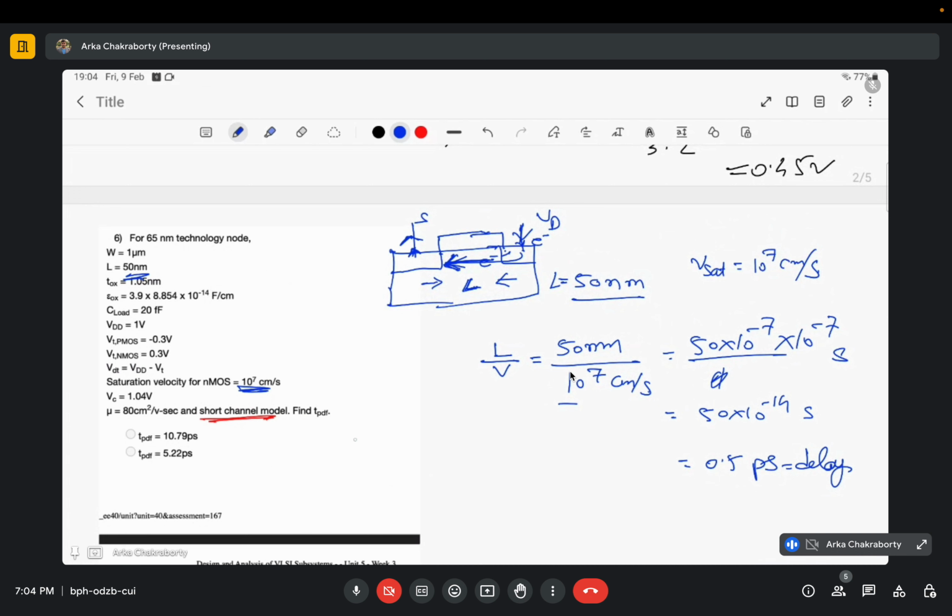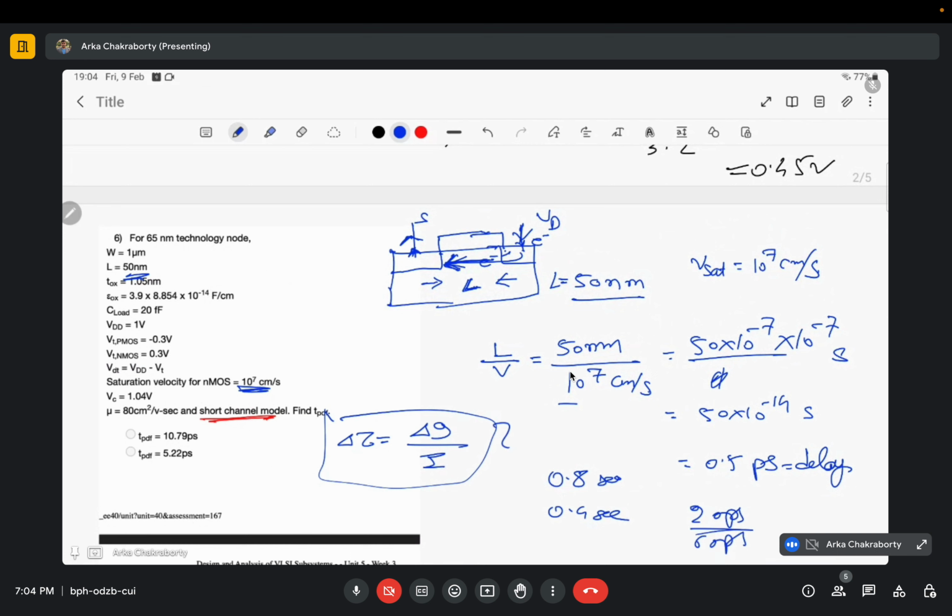If you recall your first year basic electronics courses, BJT, same thing, we can describe the delay in terms of this. So my delay, if I write by delta t, is always some delta Q by I, where delta Q is change in charge and I is the average current, or it might be instantaneous current. If you use this definition, you can get the desired expression of delay to a good approximation. Say if the result is 20 picosecond, you might get 60 picosecond, but you will get the correct range just by simply using this expression.